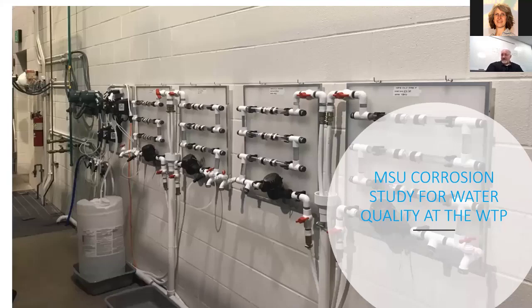There's also 3 sites out in the distribution system where we're monitoring corrosion and currently applying that same orthophosphate mixture to the system since August 26th from our go live, and we're currently in the middle of a round of lead and copper testing to monitor that, which has been state mandated.